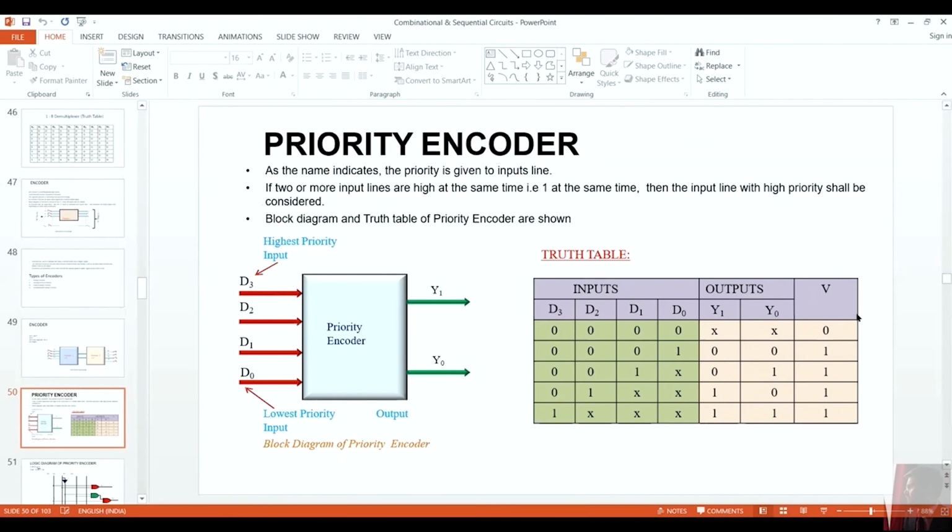You will see yourself, priority encoder. How many inputs? 4, 2 raised to power 2. How many select lines can I use? 2. The output would be 2. Okay, so the major difference we normally see over here in this case is two outputs as a priority encoder.